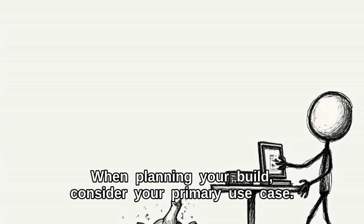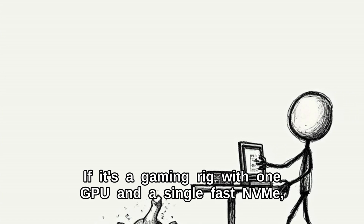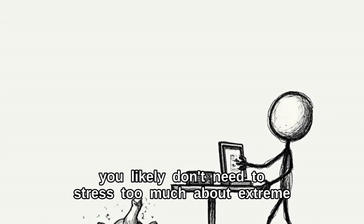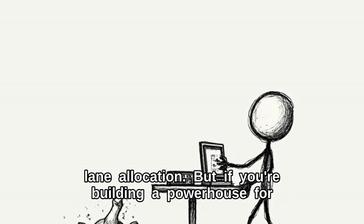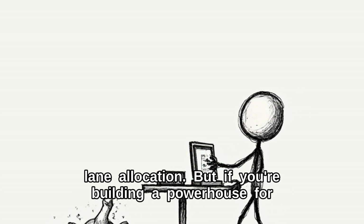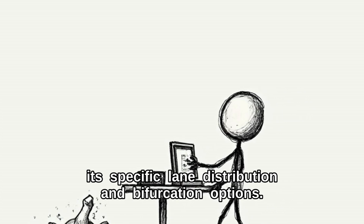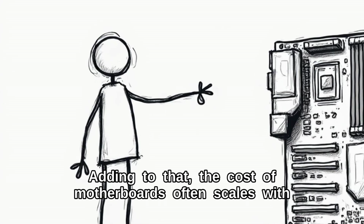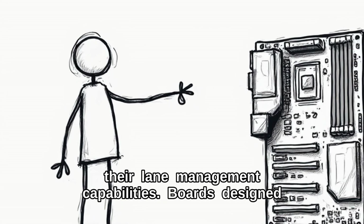When planning your build, consider your primary use case. If it is a gaming rig with one GPU and a single fast NVMe, you likely do not need to stress too much about extreme lane allocation. But if you are building a powerhouse for professional work, always check the motherboard's manual for its specific lane distribution and bifurcation options.